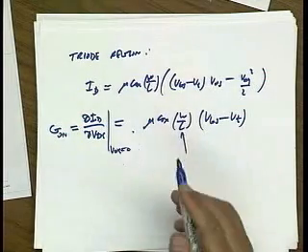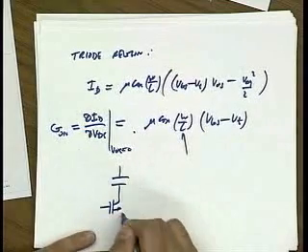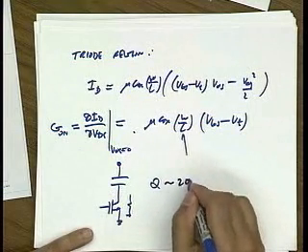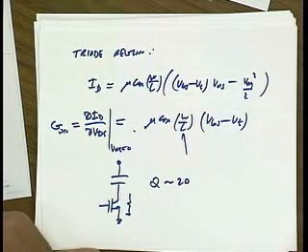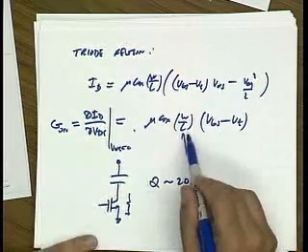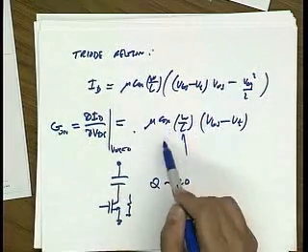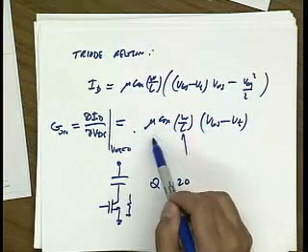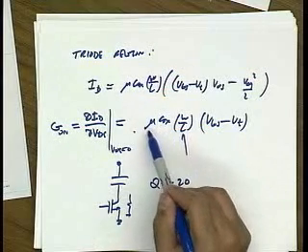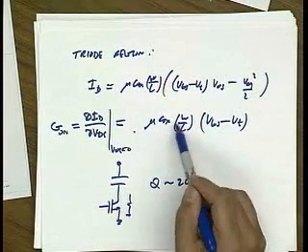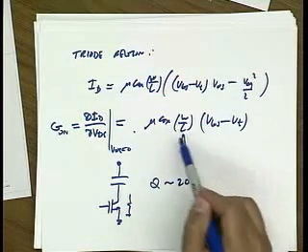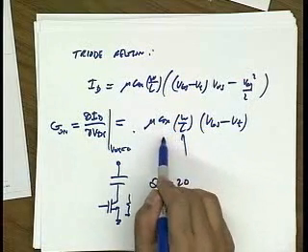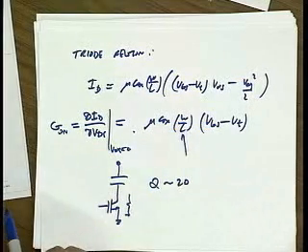If you built a cap like this with a MOS device, then the on resistance would give you Qs, let's say, on the order of 15, 20. And this is process dependent, because as process scales, basically Cox gets bigger, right? Because Tox is getting smaller. Mu is roughly constant, maybe going a little bit down with process, but L is also shrinking. So the net benefit is a huge increase, because this is epsilon ox over Tox. So the product of Tox and L helps you get lower and lower resistances.